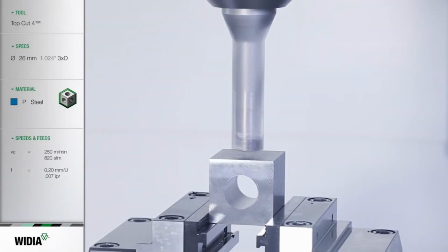Next is a much more demanding application. We are going through another hole, crossing the hole at a 90 degree angle. Usually it is possible to do this with any indexable drill, but we need to decrease the feed by about 30% to 3 times. Here you can see we are not decreasing the feed, so it depends on the design of the drill. In general, the advice is to decrease the feed in the cross-hole section, but not every time.